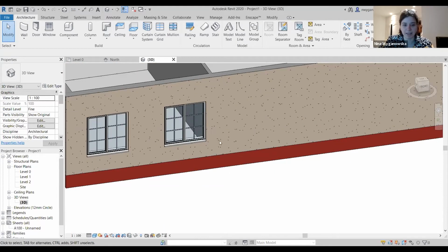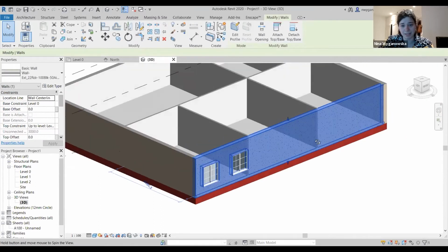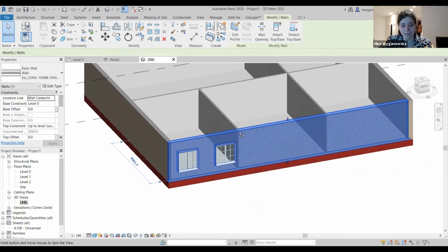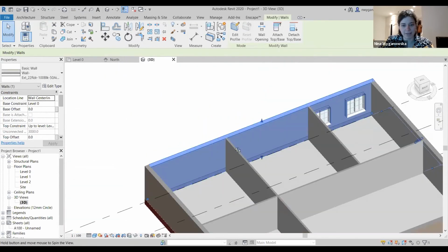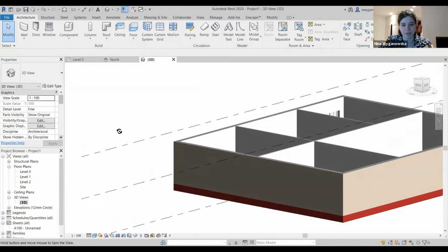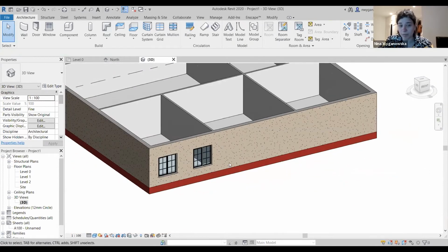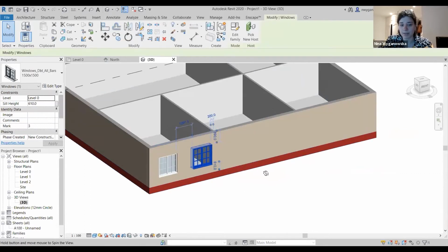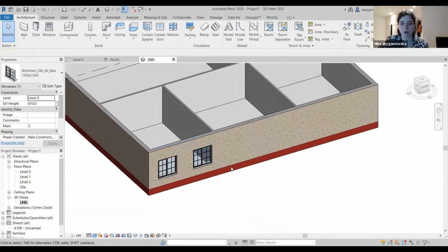So for spinning, normally, so you don't go into the air, you can click an element, click the middle of your mouse and shift, and that allows you to spin around the element itself. So if I don't click the element, it will spin everything around. And if you have a big model, that is problematic because it might spin you inside the building instead of actually spinning you somewhere else. So if I click around a material, it will just spin me around that exact object.